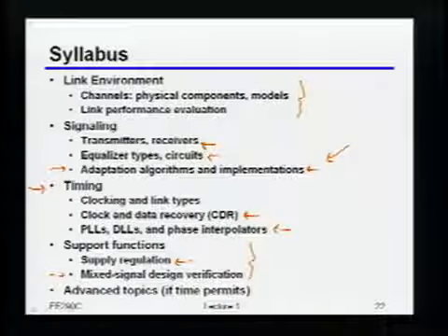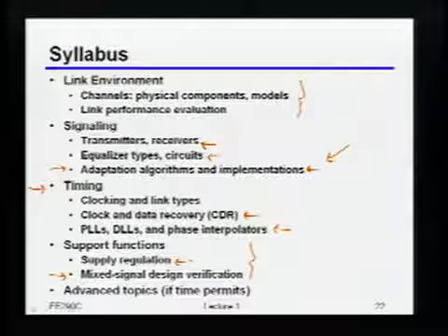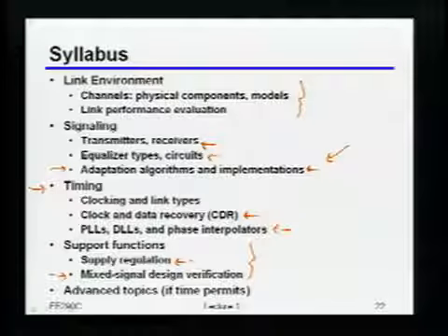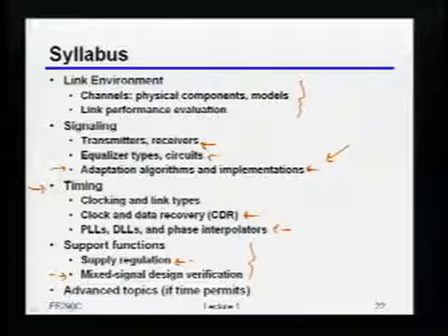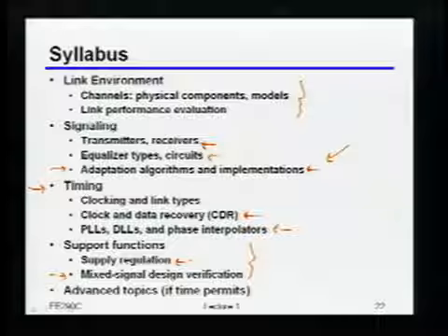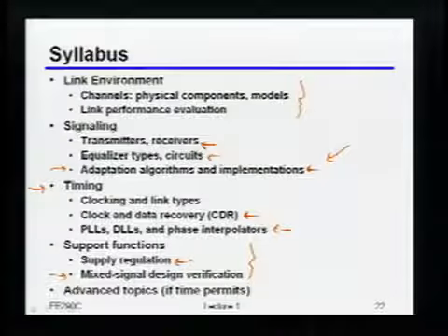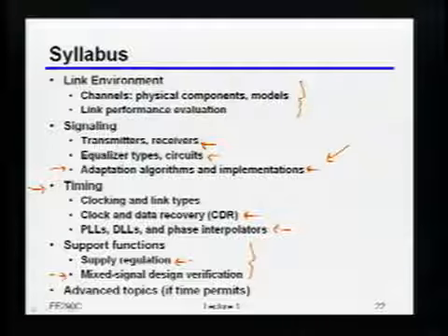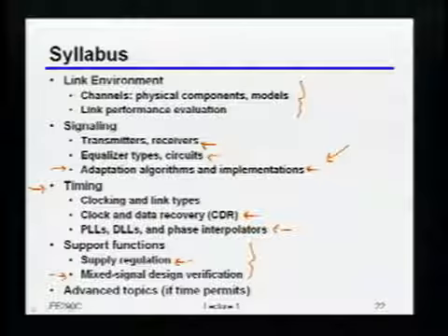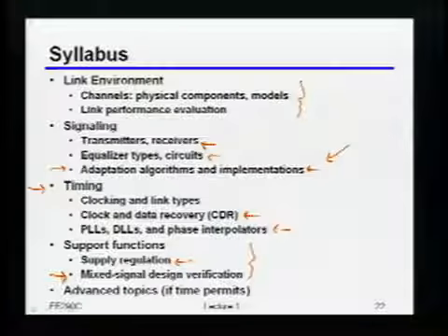And then the other thing that I'll spend a little bit of time on, which is maybe not your standard circuits material, is how in the world you actually verify that this chip that you're building is actually going to work when you get it back. Okay, so we'll talk about how you really do some mixed signal verification. Because I've personally worked on multiple chips where things like digital buses were inverted or flipped, or there were hold time issues and just really stupid errors that cost literally man-years of effort just to go down the drain.